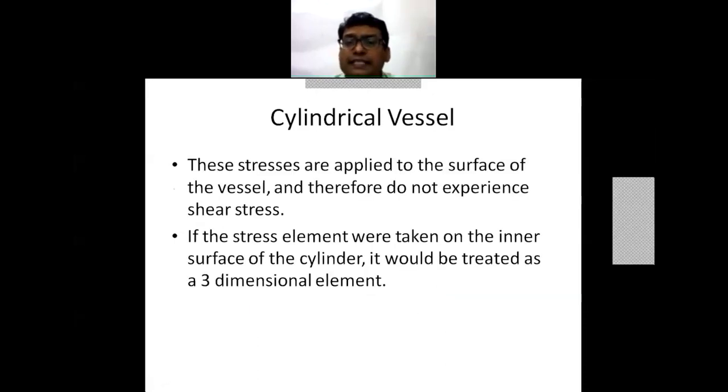Now the stresses are applied to the surface of the vessel and therefore do not experience shear stresses. If the stress element were taken on the inner surface of the cylinder, it will be treated as a three-dimensional element.